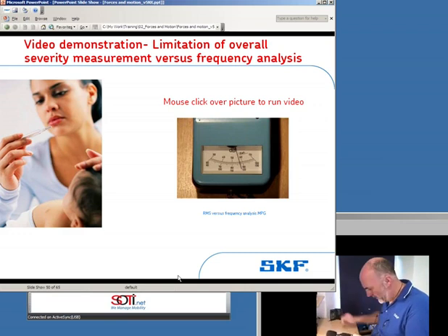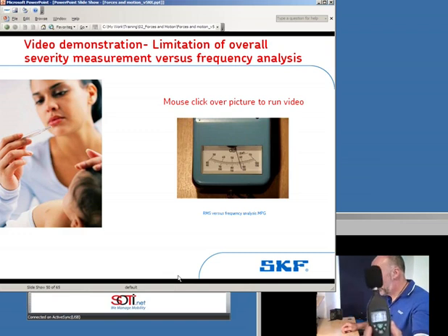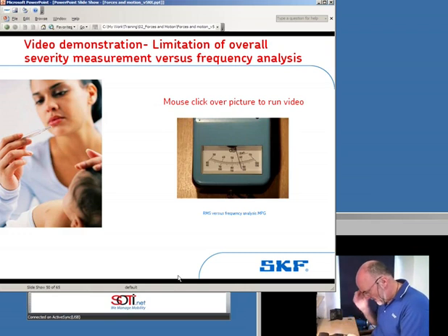I've got my simple sound level meter that's going to give me a reading. I'm going to put this onto C weighting, and we'll put it onto a slow reading. I'm going to create a noise, and then create a tonal noise on top of it and take a reading.